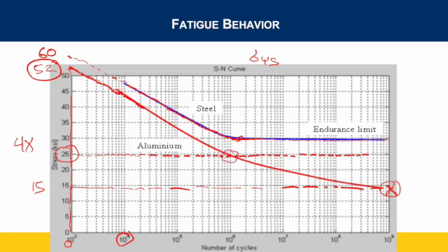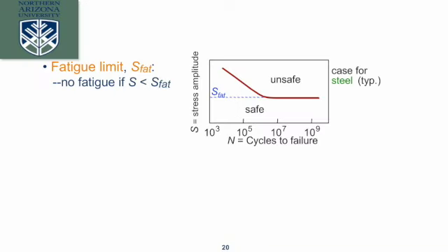However, if we go the cheaper route and use aluminum instead, this material will break right about 1,000,000 cycles, 10 to the 6th, right? So steel will continue to last, whereas the aluminum will break after 1,000,000 cycles. Okay? Even though they had very similar strengths to start with, picking the right material is very important. This fact that steel in particular has an endurance limit where it stops losing its yield strength is a really unique property.